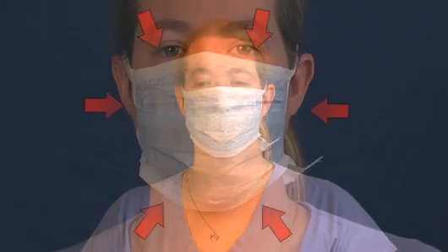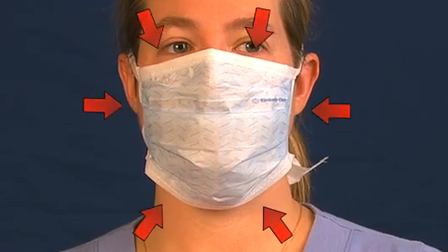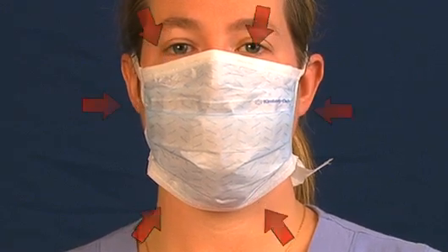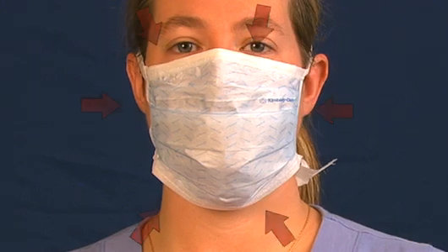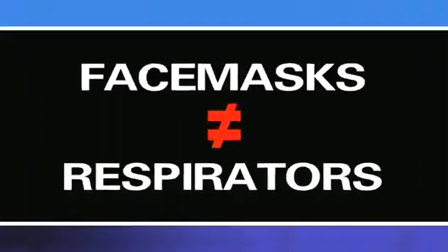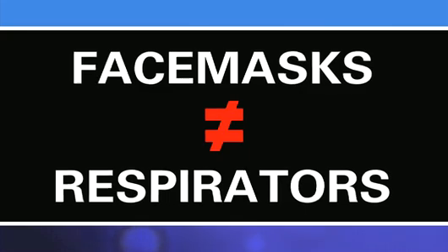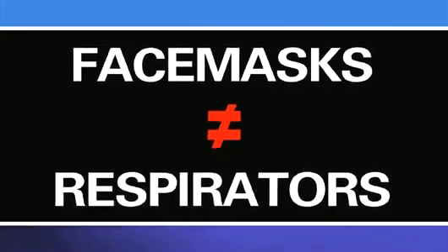However, face masks are not designed or certified to seal tightly against your face or to prevent the inhalation of small airborne contaminants. During inhalation, small airborne contaminants pass through gaps between the face and the face mask and the material of the mask. Remember, face masks are not considered respirators and they do not provide respiratory protection.